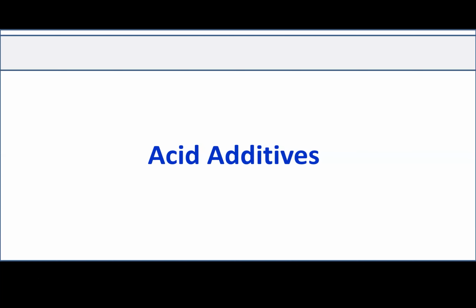First, each well will have some sort of a reservoir model associated with it, and you calibrate this model, and you have something called type curve analysis when you are expecting reduction in the production with time. Second, you do well testing, pressure build up or drawdown test, and from these two items, you can define or calculate the skin factor. If you find you have a zero skin factor, you are good.